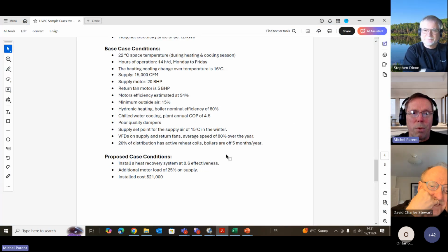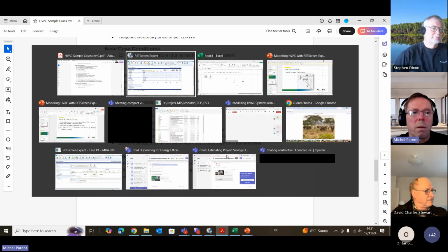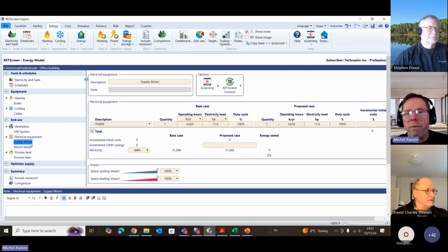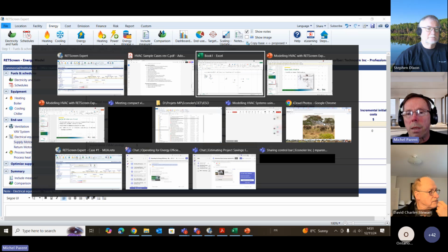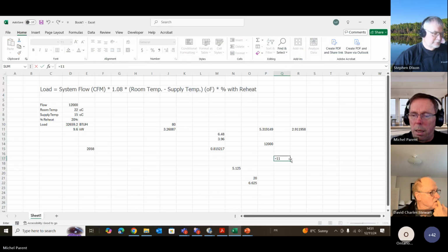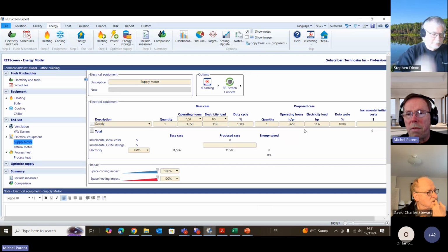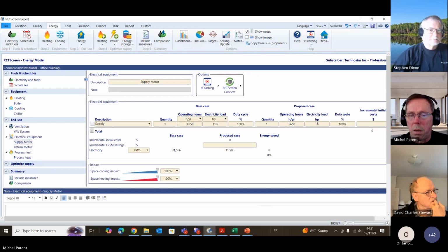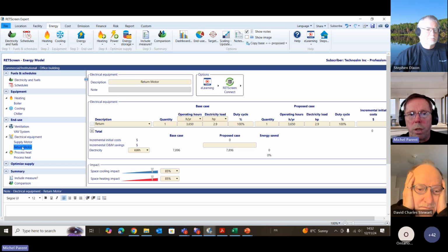Because we'll have, again, if we enter 25% more, I'm not even going to account for any fan loss. I'm just going to take my 11.6 times 1.25. That's 14.5. And you don't forget to do it on a return.